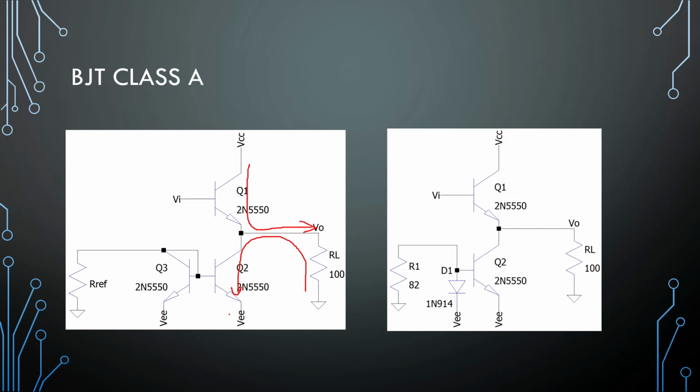This is technically a current sink. Okay, so positive will be supplied from the top, negative will be supplied from the bottom. Right, so the current of this current source is also the peak current that you want on this load resistor.